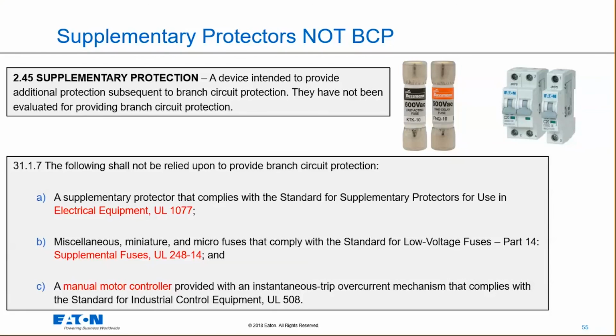A lot of times you'll see supplemental fuses, for example, inside of a Fluke multimeter in many cases. That fuse is in there as supplemental protection, just in case you do something you're not supposed to, maybe you touch the wrong thing with your meter. Hopefully that fuse is going to pick it up and not short things out, not cause any damage or hurt people.